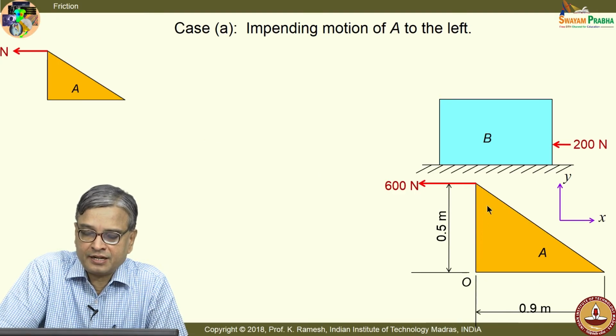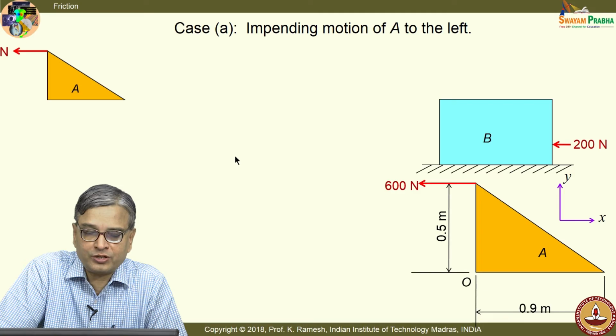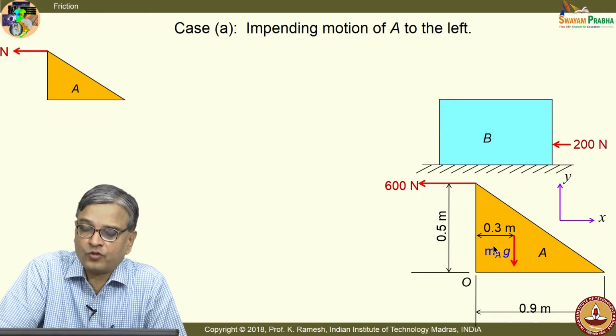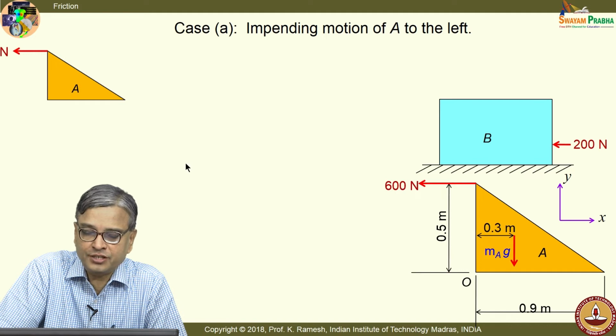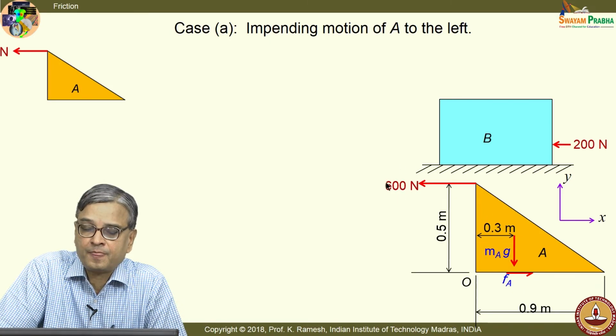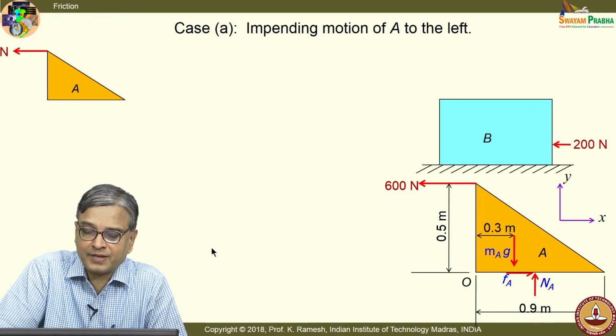So, I have the free body drawn here. I have to put the forces, and I have the weight acting like this. The question is, what is the value of WA we should find. And I would have in general a frictional force developed, and this direction of friction opposes the force of pulling. And as we have discussed already, I would not put this normal reaction passing through the centroid. I would put it at an arbitrary position. Let that location be at a distance of d.